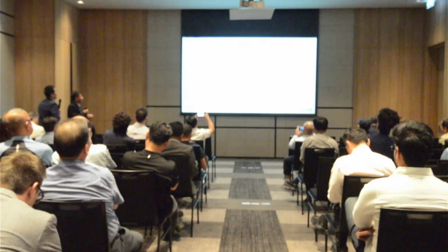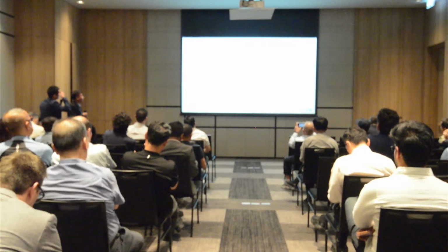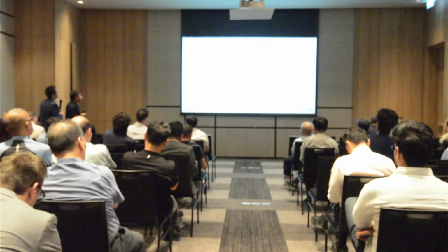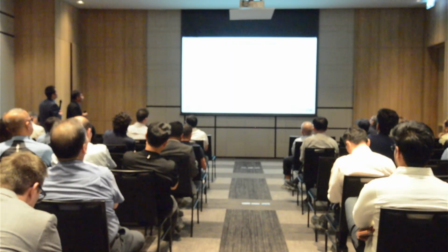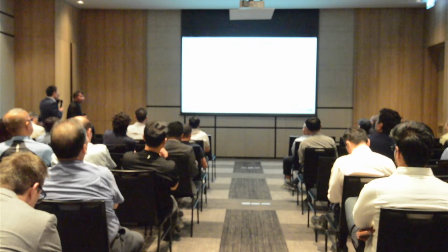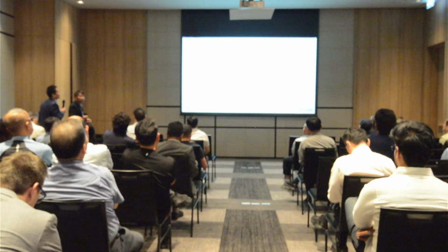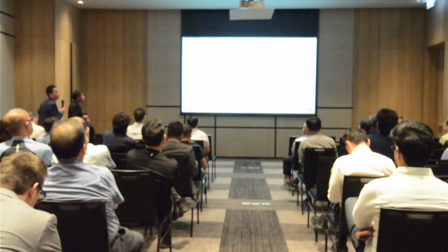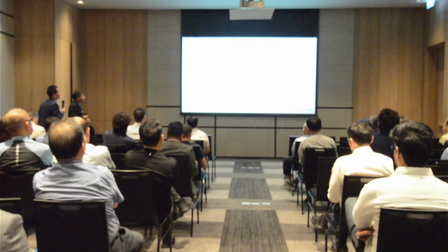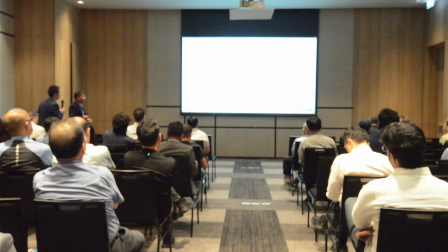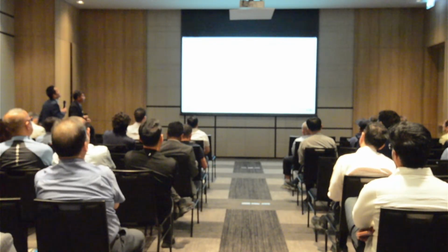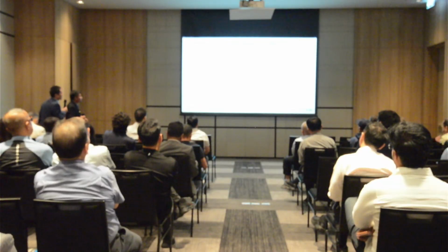Then we calculate again, using the machine's maximum at 50% and minimum at 30%, using the middle range. We use a gate speed from a minimum of 30 to a maximum of 50 meters per second, and follow the process window. The point is to be in the right process window.